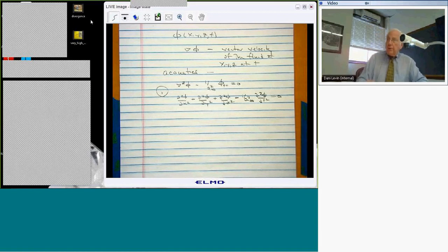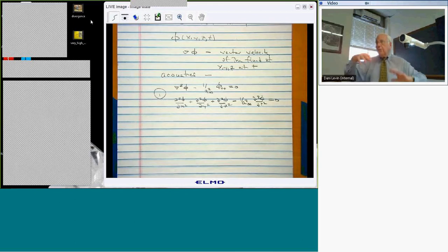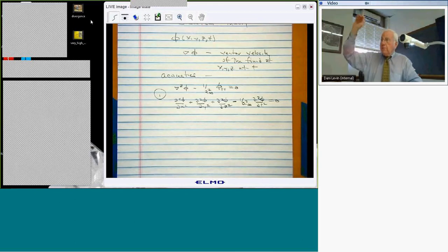All right. And what are the boundary conditions, therefore, you might ask? Well, one is that if I have an airfoil in a flow and I go way far away from it, you might think that nothing much happens there. Well, that's sort of true. Things do tend to die off as you head towards infinity, but in some cases the waves propagate out, and according to the classical theory, they don't dissipate because we left out viscosity, right?